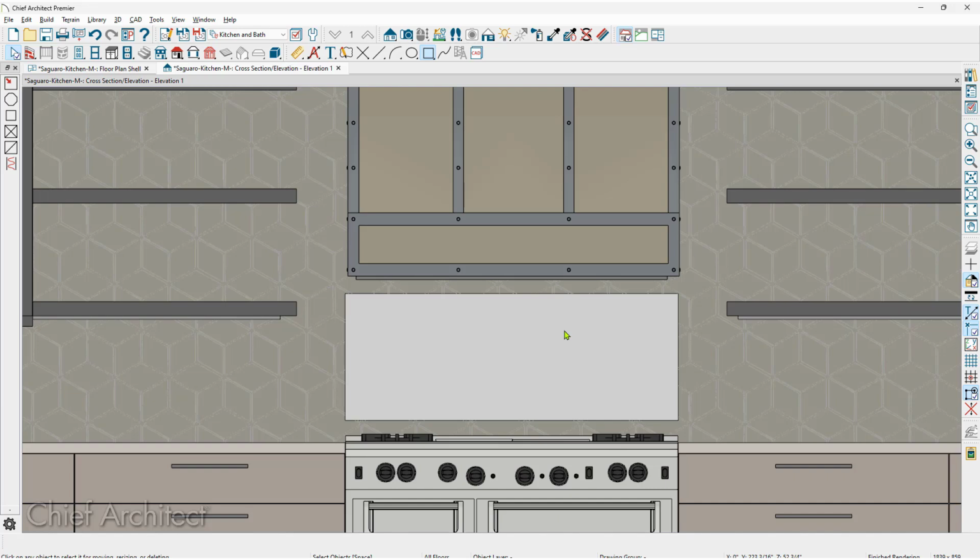To create the frame molding, I'm going to use the CAD box tool. You'll see this up in my upper menu system. Using this tool, I'm going to pick up a snap on the hole, and drag until it snaps onto the other side. This has created a CAD polyline box.